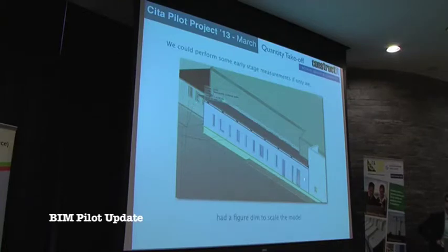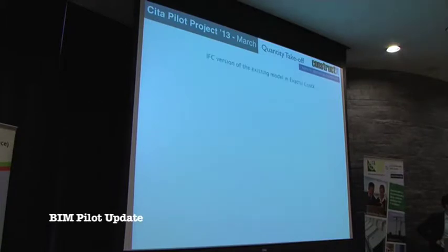You can see I've measured this little area of blockwork here, and it's coming in as a length of 2.4 metres with an area of 0.1487 metres squared. So there's an issue there. If you're working with SketchUp, architects especially, just put a dimension on it. Put a dimension on somewhere that it can be scaled up. It comes in great, but we can't do a huge pile with it.